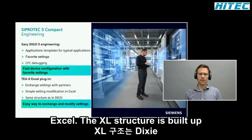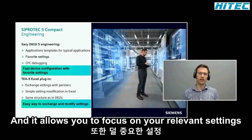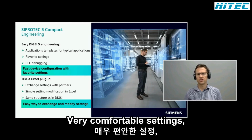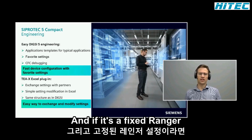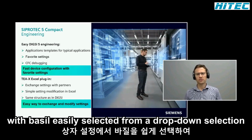The Excel structure is built up like the DIGSI5 structure, and it allows you to focus on your relevant settings by hiding the less important settings via group and ungroup buttons. Excel provides, therefore, a very comfortable way to adapt your settings. All the cells in light yellow colour indicate settings that can be modified. And if it's a fixed range of settings that can be chosen, these are easily selected from a drop-down selection box.